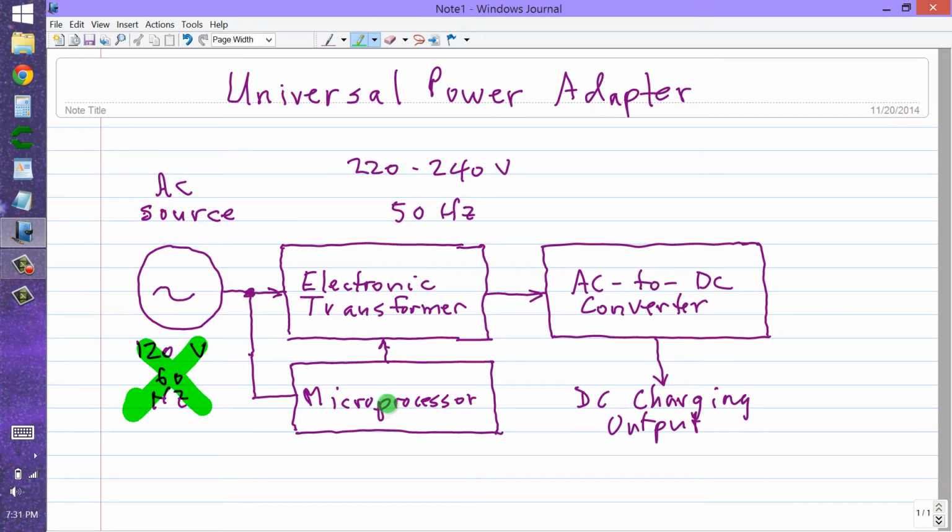Most of the world, I believe, uses the higher voltage. I guess the objective is that for a given amount of power, you have to draw less current, so it produces less current in the wire and therefore less heating in the wires. But of course, the higher voltage is more dangerous. Now, the 50 hertz or 60 hertz is a little less important if you're going to convert to DC in the final result.